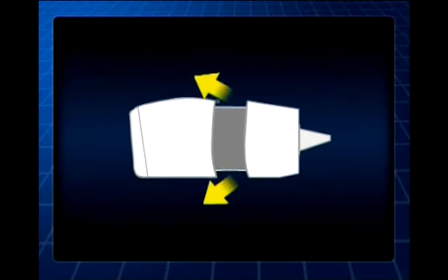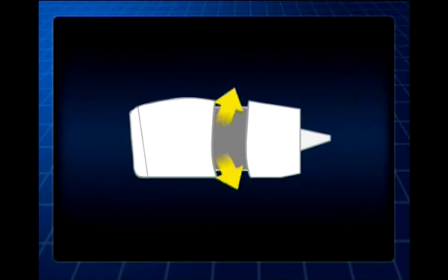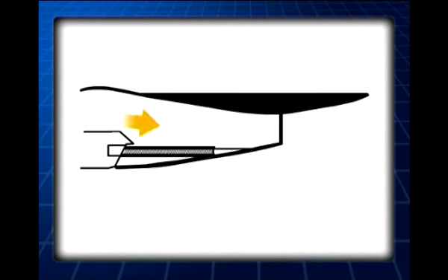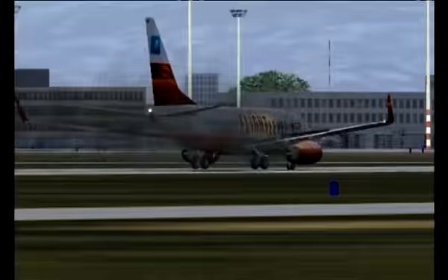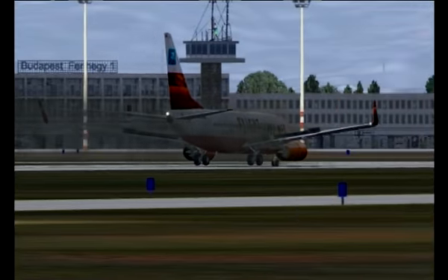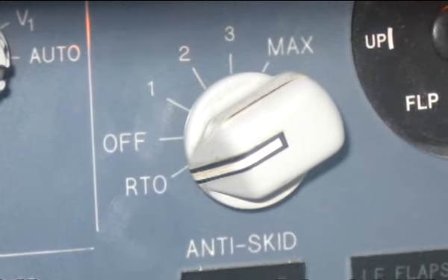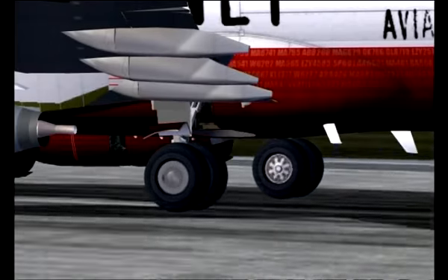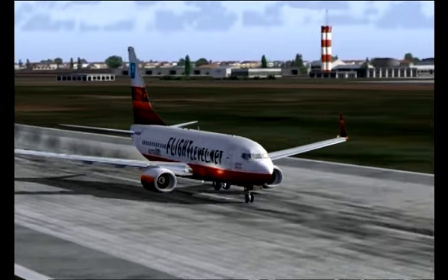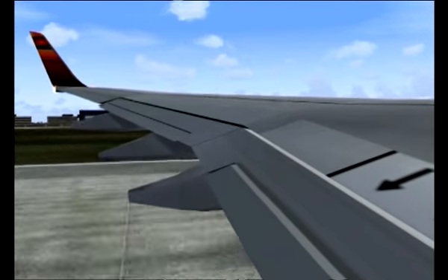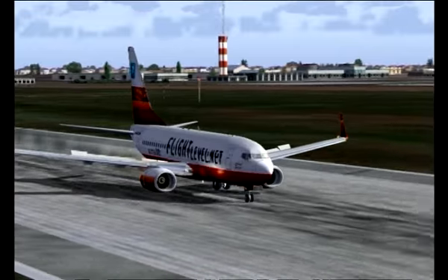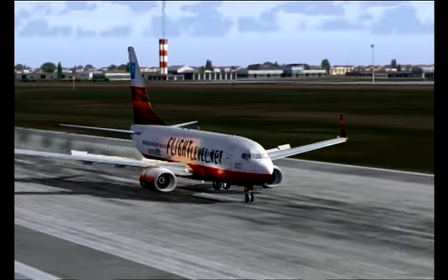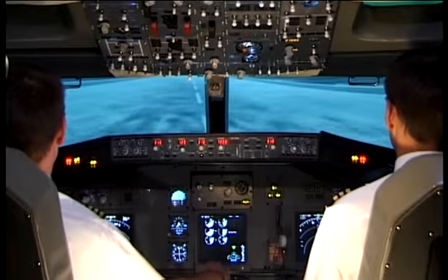The thrust reverser deflects hot air generated by the engine and, as its name suggests, reverses the direction of thrust, thus providing efficient braking while the aircraft is rolling at high speed. At the same time, the automatic braking system engages, providing maximum braking power to the wheels. Large control surfaces called spoilers deploy from the top of the wings to reduce lift, making the main wheels touch the tarmac more firmly, which improves wheel braking efficiency.